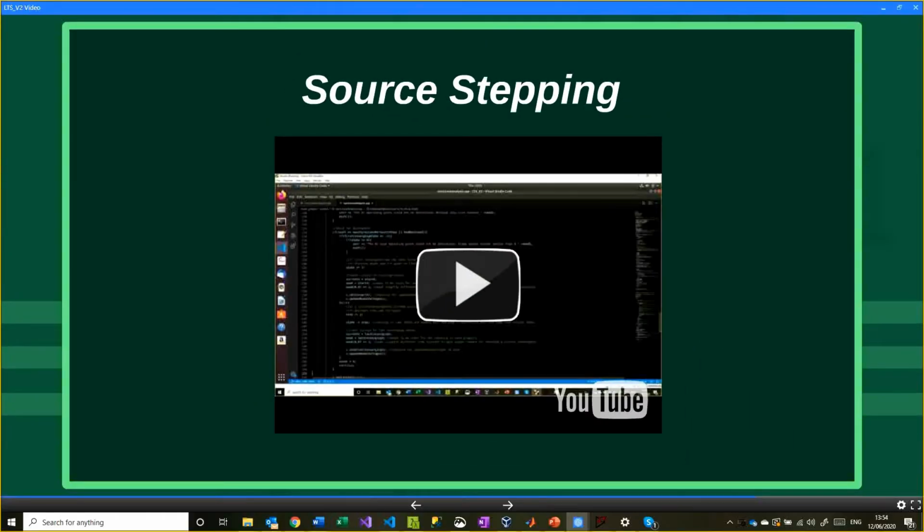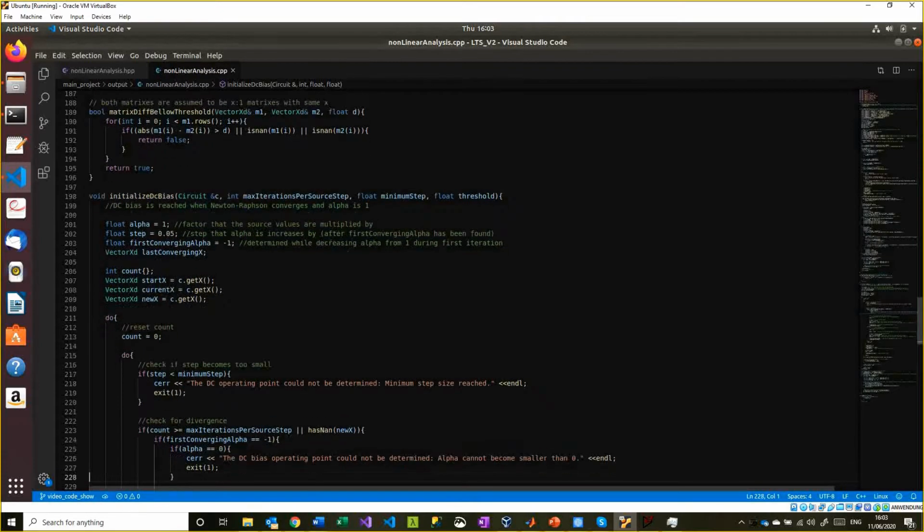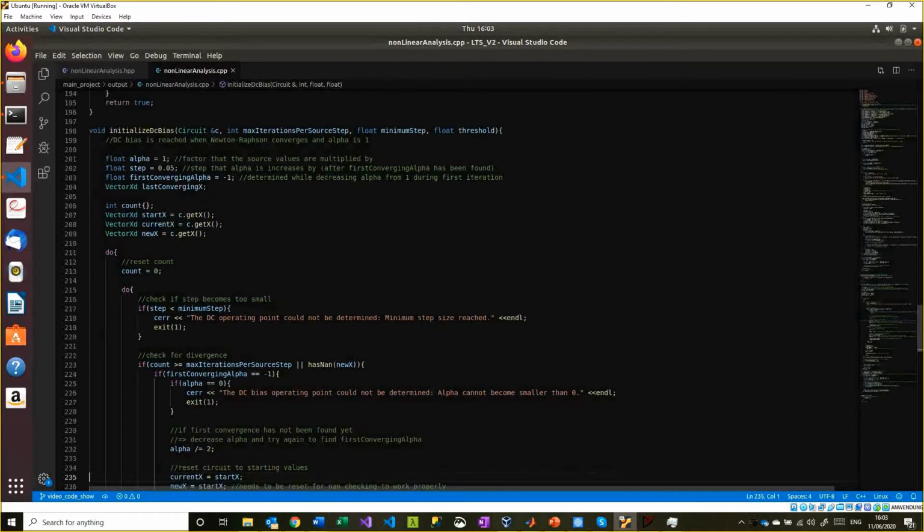One problem with nonlinear components is that Newton-Raphson tends to diverge if the initial guess is far off the stable solution. This occurs when sources are non-zero values. To remedy this, source stepping is used. This method tries to reduce this difference between initial guesses.